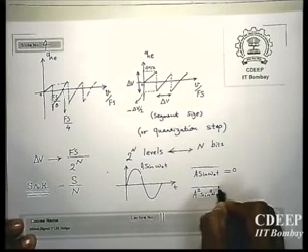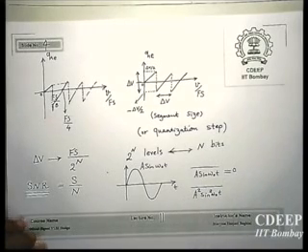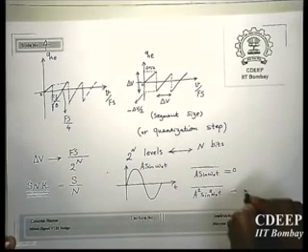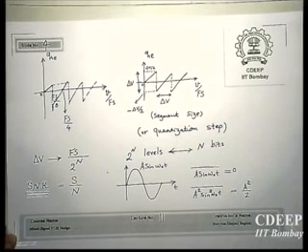the average value of the signal square, if we normalize and consider resistance equal to 1 ohm. So if you apply this signal across a resistor with the value of 1 ohm, the average of this value will be the amount of average power which is dissipated in the resistor in one cycle. So this is the definition of average power. And then you also know that this will be A square by 2, right?